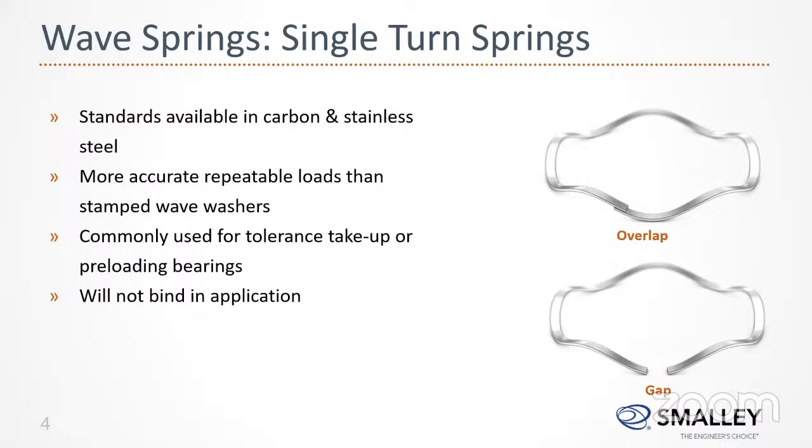Whereas here, we take a wire, flatten it, and then wind it. So the circular grain structure is not damaged. This possesses superior strength and stability and offers the spring force until the end of the assembly's life cycle.